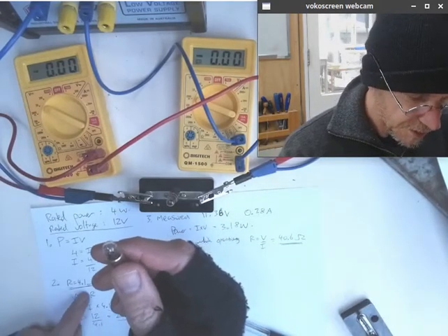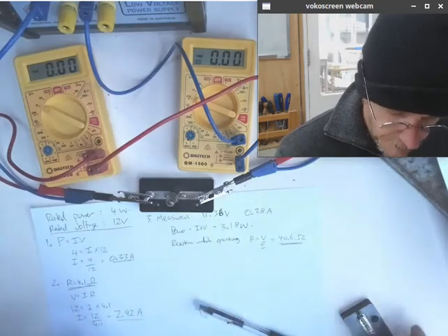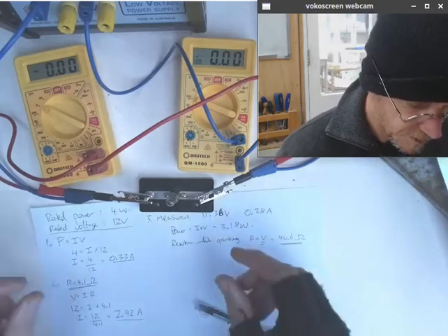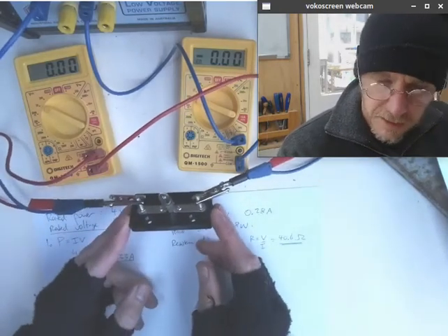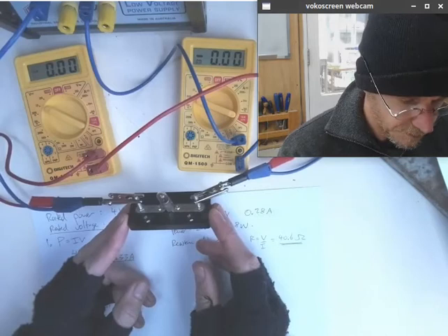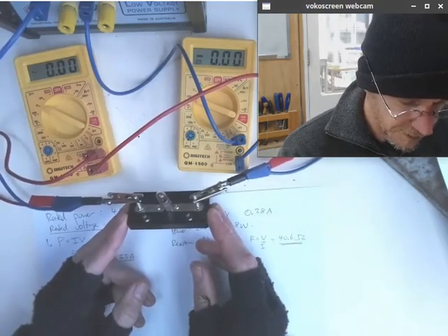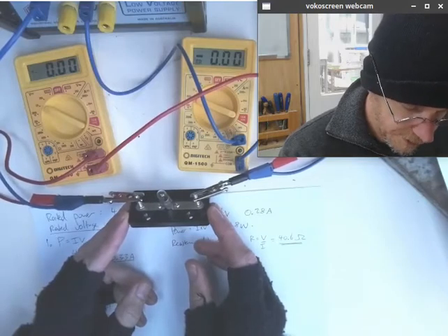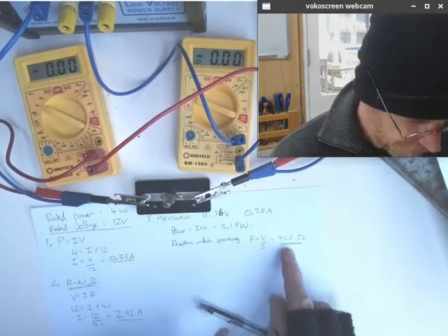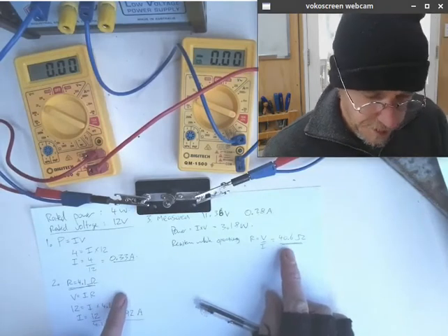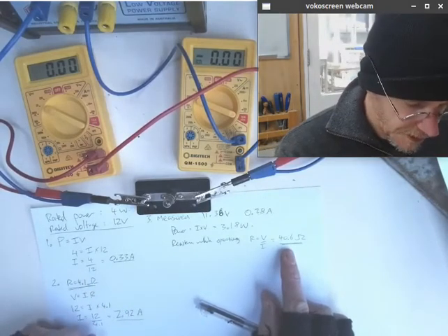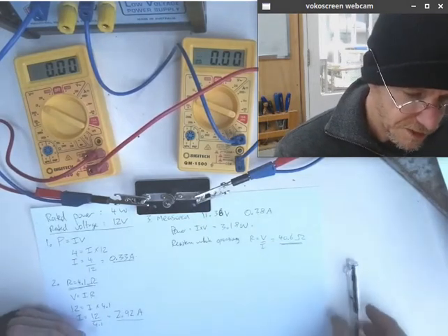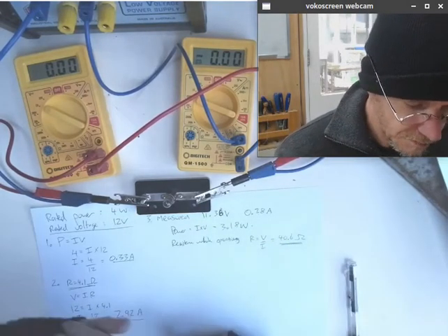Its resistance was only 4 ohms. On the other hand, when it's running close to its rated voltage, or when it has its rated voltage applied, it's running at the temperature that it's intended to be when it's operating, and suddenly it's actually 40 ohms. So a light bulb is an example of a resistor that is most definitely not being used in a way that stays true to Ohm's law throughout its scale.